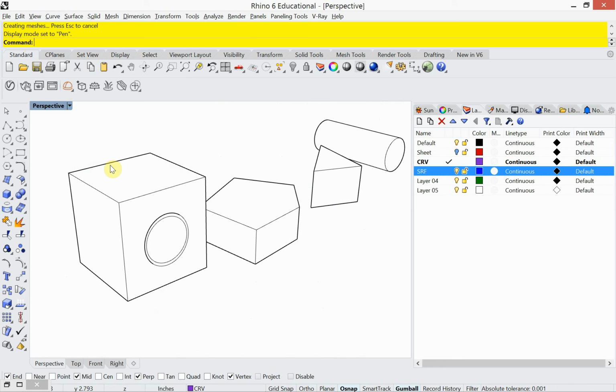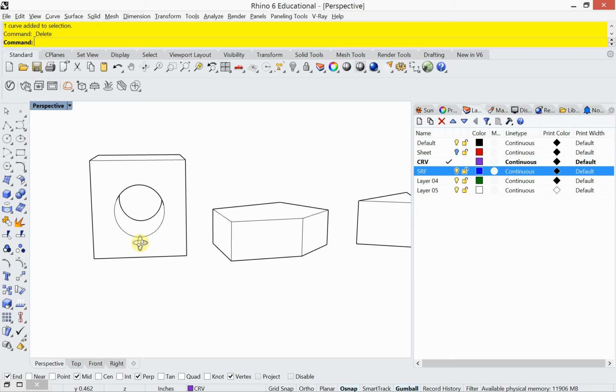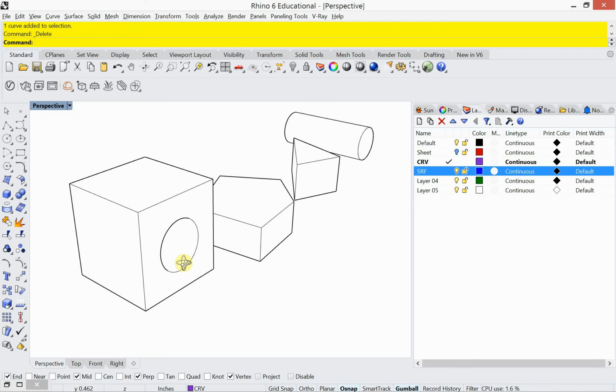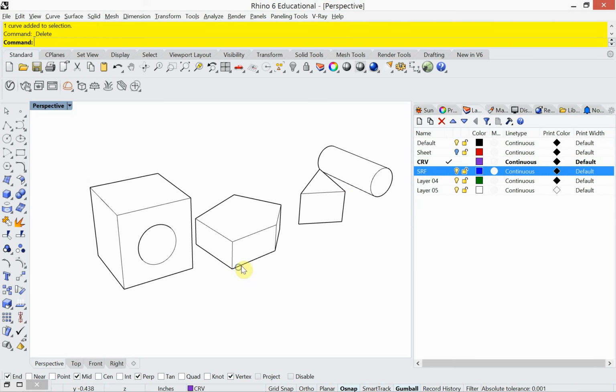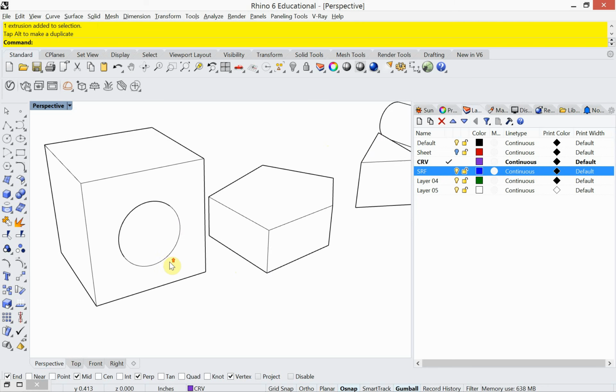Alright, so I want to look a little more closely at this. So let's see, that's the original curve. I'm just going to delete that. Okay, so I see that it has an issue. I like this pen mode, and I imagine it's just going to keep getting better. It has an issue with showing me the bottom edge of this object as a heavy line weight. It shows me the complete outline here, but it's having trouble with that. So let's just address it.